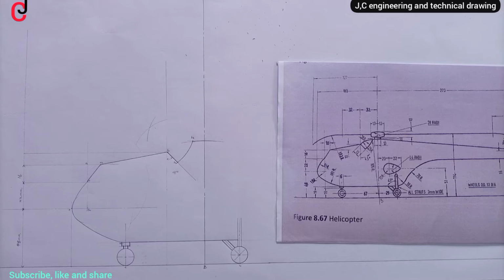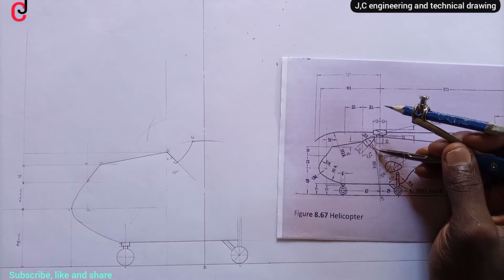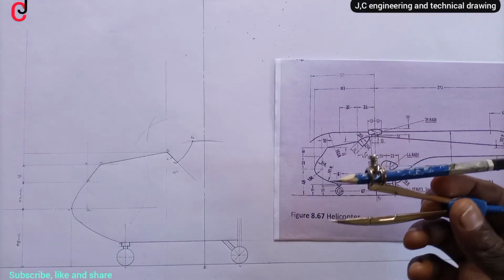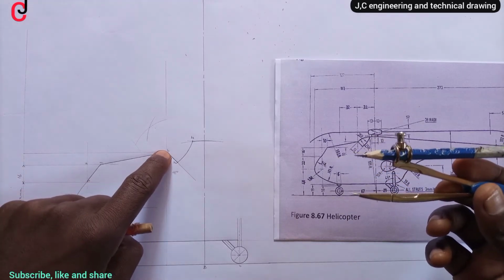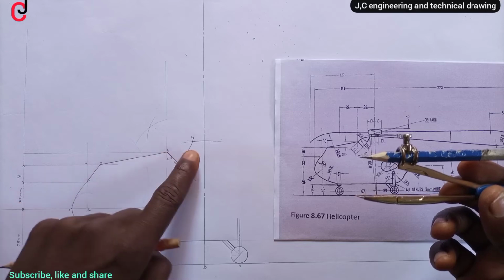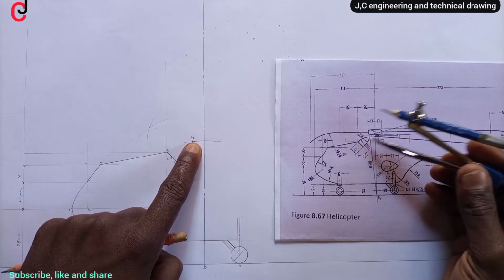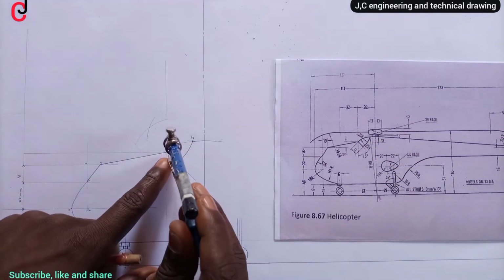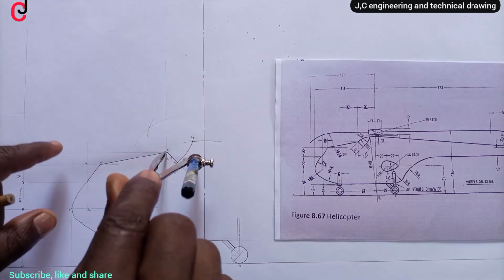Now also we'll open our compass to 25 millimeter radius, using point B1 and point B3. Points B1 and point B3 with radius 25 millimeter. Place a compass pin at point B1, scribe an arc.